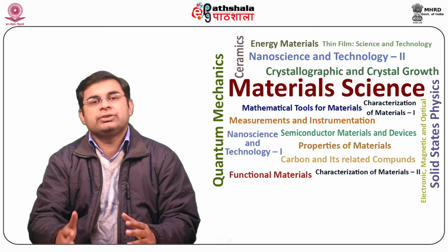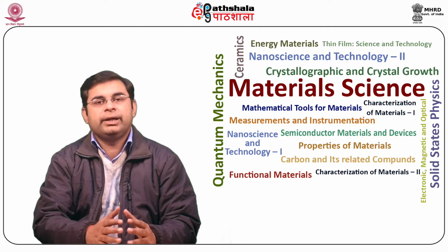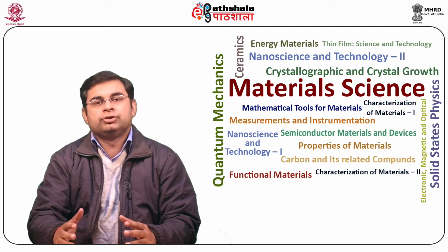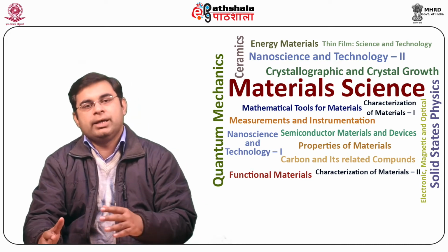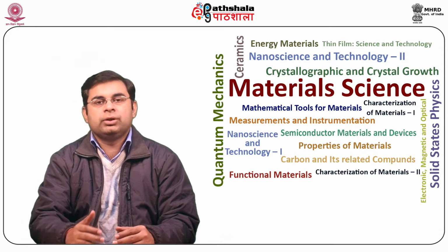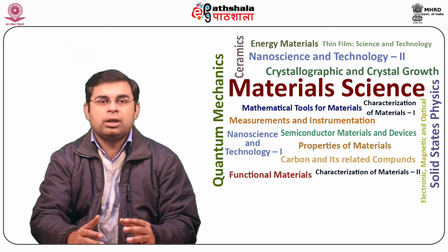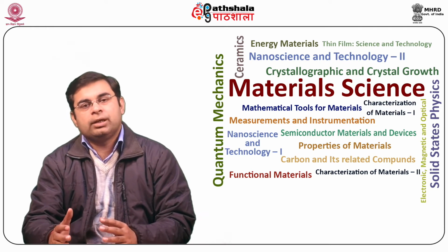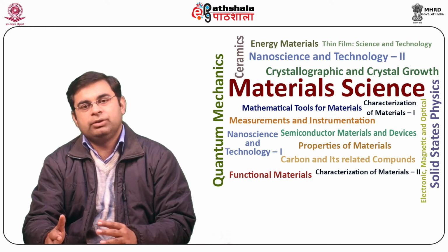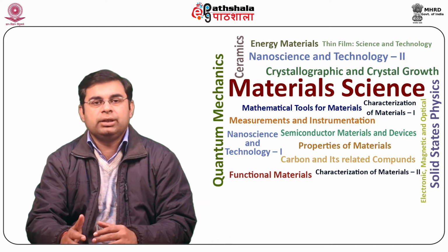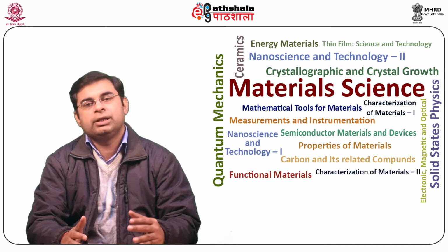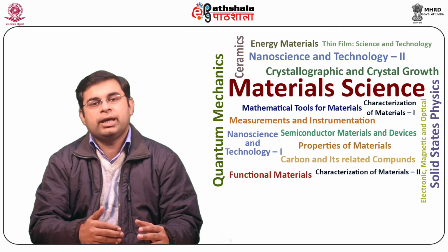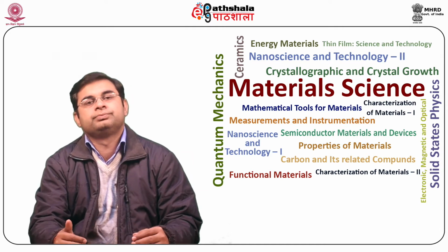There are various techniques like spreading resistance profile (SRP), stripping Hall profile (SHP), which give additional information about the carrier mobility, and capacitance voltage (CV). Additionally, the measurements of Schottky diodes have been used to enumerate the carrier concentrations.